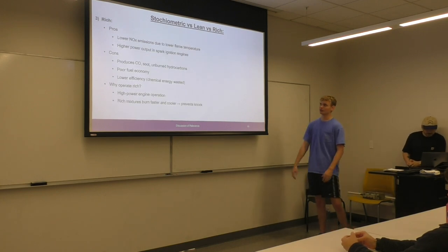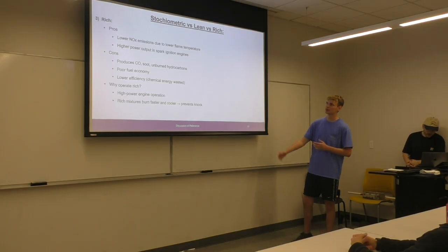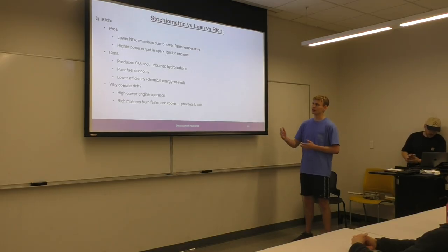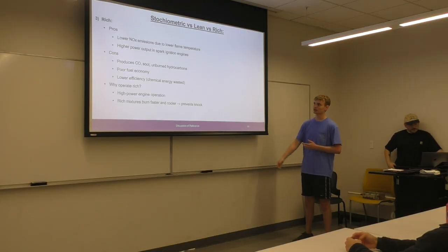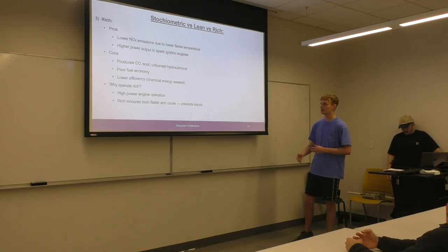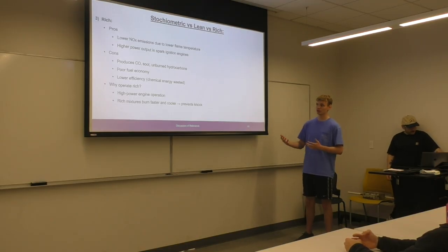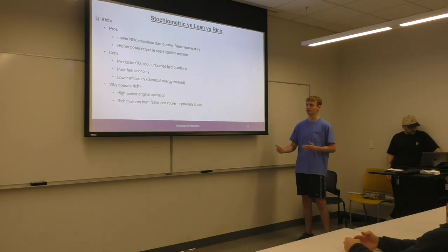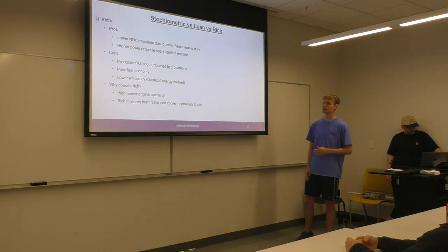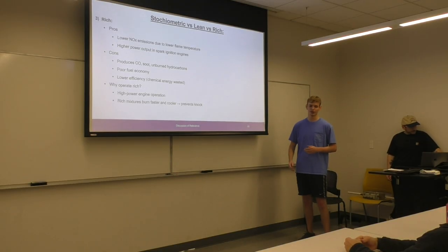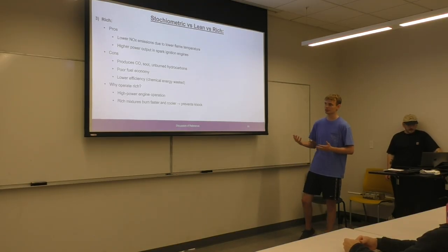And then lastly, for rich, the pros are lower NOx emissions due to lower flame temperature, and higher power output in spark ignition engines. The cons are it produces CO, soot, and unburned hydrocarbons. Again, those are your emissions. It has poor fuel economy, and it has a lower efficiency because you're going to be wasting chemical energy. We want to operate rich because it produces higher powered engine operation. And rich mixtures also burn faster and cooler, which prevents knock.